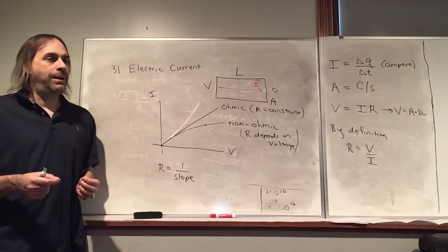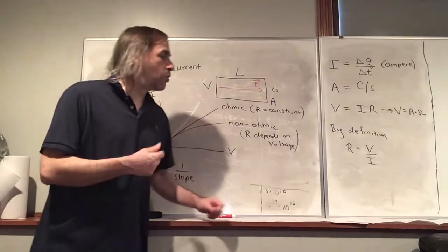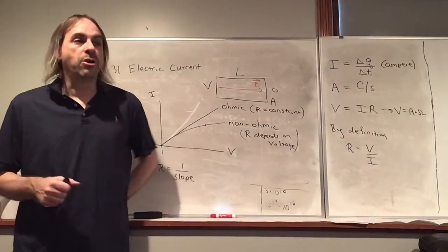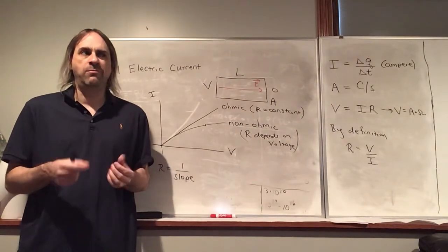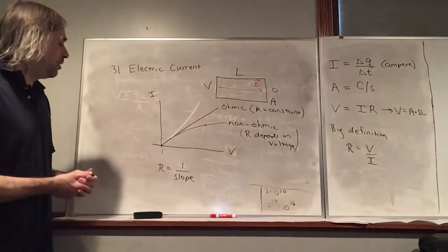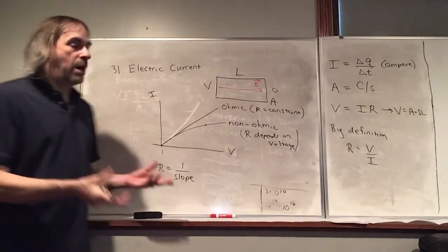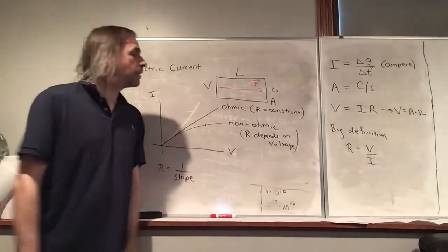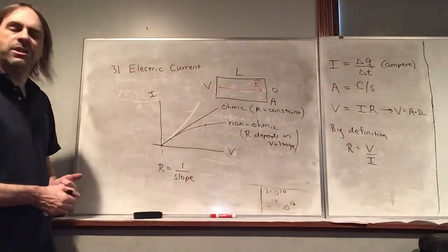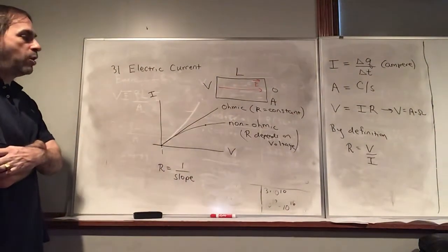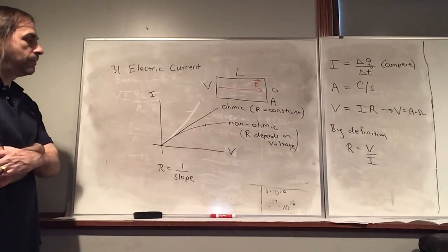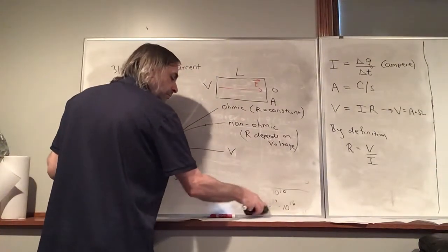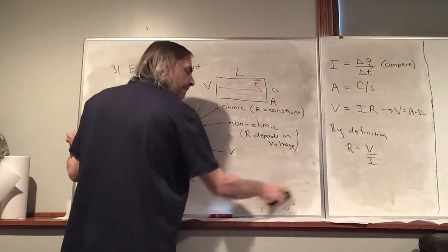If you turn it on, I'm pretty sure the reason a normal light bulb does not have a constant resistance is that they heat up very much. Like those old incandescent light bulbs, you have a filament that you heat up to, I believe, a few thousand degrees. When the light's off, it's at room temperature, and then when you heat it up, it goes through such a great temperature change that it affects the resistance. So I'm just assuming that's why a normal light bulb does not obey Ohm's law. That seems reasonable to me, but I never actually looked that up.